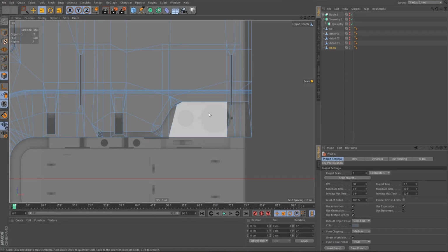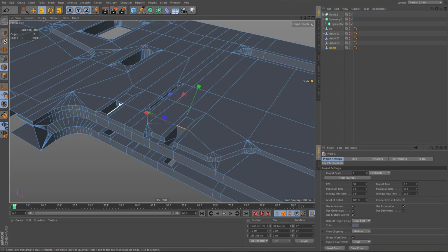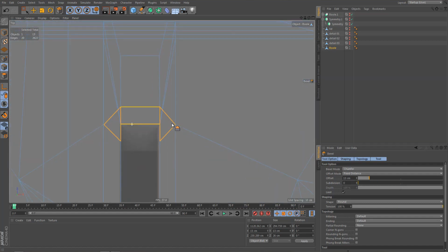Before I cut these holes into the panel, I'm going to add this rectangular detail, and we also need to change the areas here. You can see we have 2 slanted surfaces here. So let's go ahead and add those. And the way I'm going to do that is I'll select these edges and I'm going to bevel them. And I don't want to use any subdivisions here. Let's jump to the top view. I'm just going to increase that bevel a little bit to about here maybe.